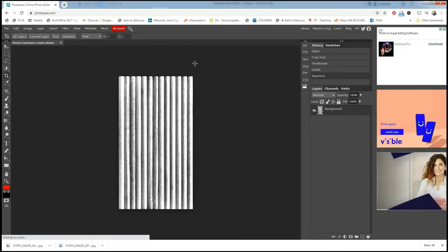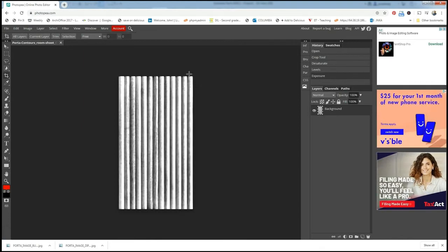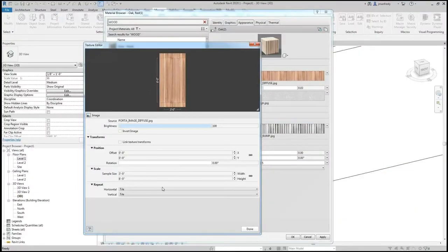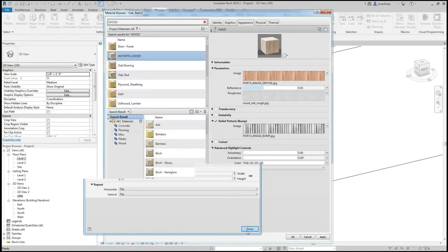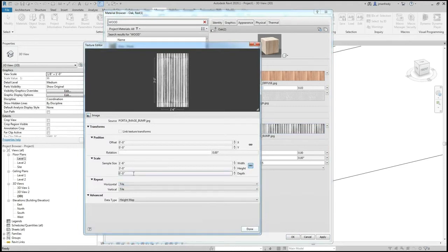I'm using feet and inches. So 26 inches across. Now, I made the walls 8 feet tall. So let's say it's 26 inches across, 8 feet tall, as an example. In Revit, I have to add that information in here. This image is 26 inches across and 8 feet tall. To enter these numbers, turn off this little link here. But that's the image size, 2'2" by 8 feet. Same thing happens here.